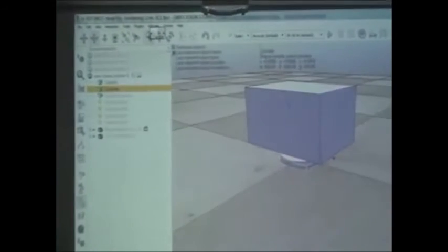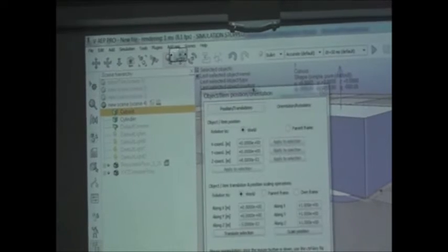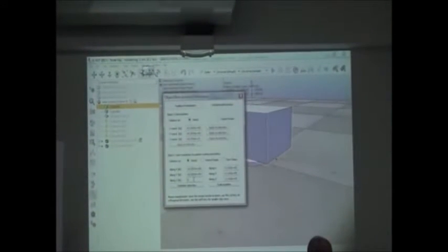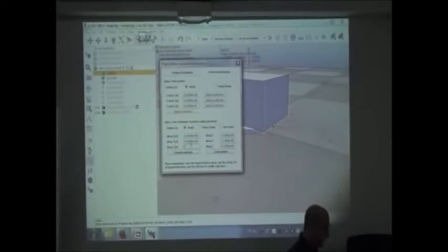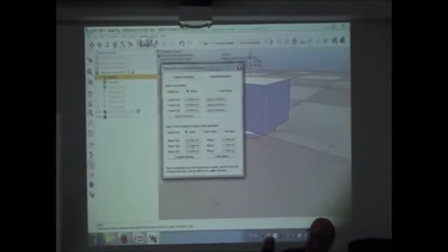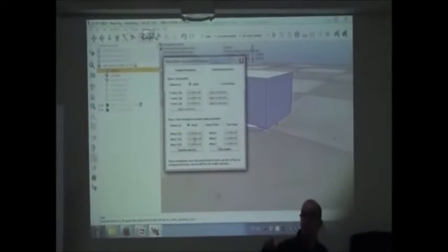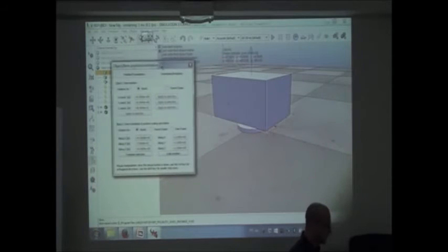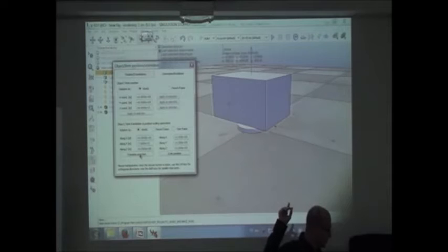To do that, you select the cube, okay? Once the cube is selected, you click on the position, the translation window. Here, just put 0 because we don't want to translate anymore in the z direction. And we want a translation in the y direction by minus 0.07. So here I will be writing minus 0.07, and I will be clicking only once. Look what is going to happen. Yeah, it's exactly what we wanted to do.